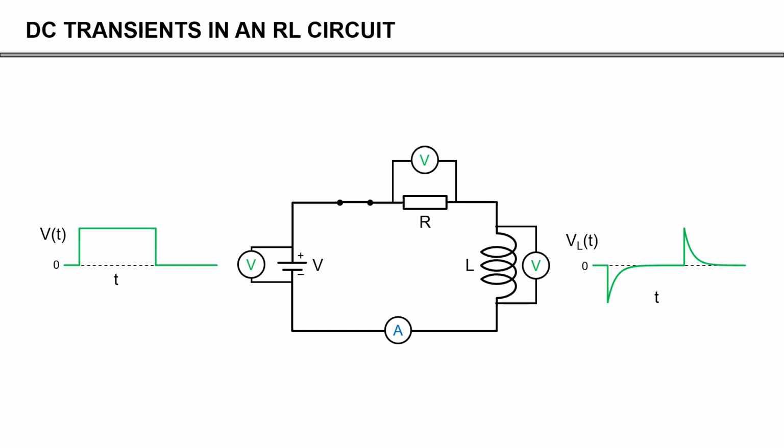Now the resistor basically experiences the sum of both effects. And so you can see here now the resistor has a profile like this. And then the current follows that profile. So indeed you can see that the presence of the inductor basically leads to a slowing down of the change in current, right?